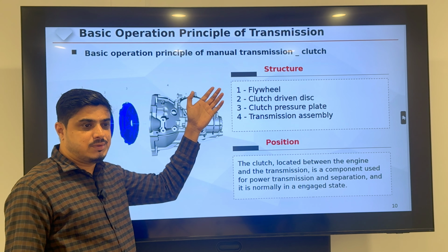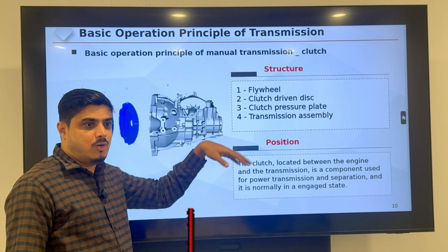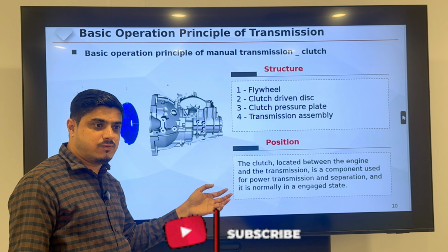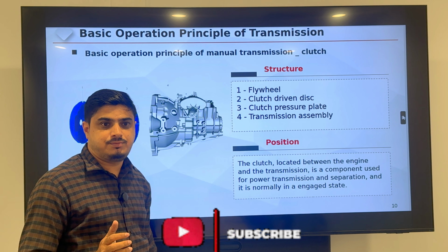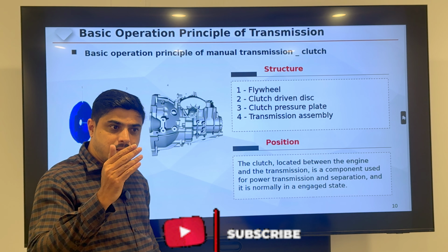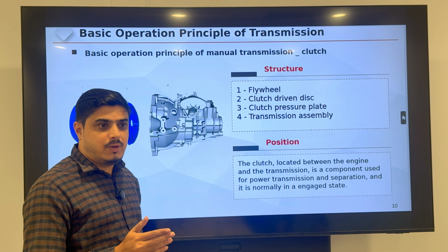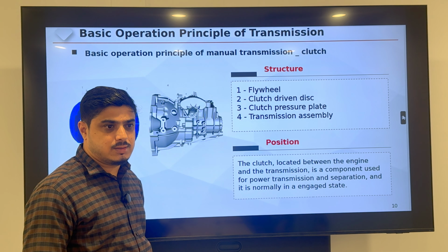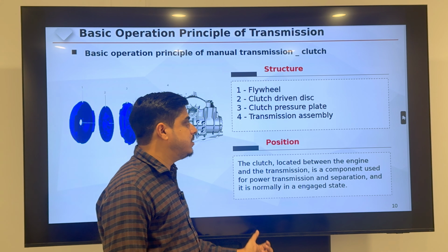to the speed limit for that particular gear which you want to shift. If you are running in the fifth gear, already at 100 or more than 100 speed, and you want to shift into first or second gear, it cannot happen. You have to bring the car to that particular speed where the gear will allow you to shift into first and second gears, right?